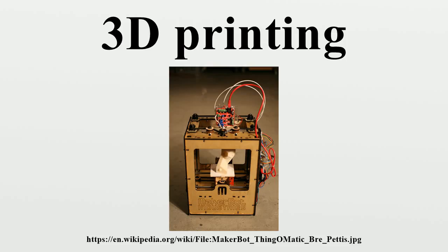Inkjet printer systems like the Objet PolyJet system spray photopolymer materials onto a build tray in ultra-thin layers until the part is completed. Each photopolymer layer is cured with UV light after it is jetted, producing fully cured models that can be handled and used immediately, without post-curing. The gel-like support material, which is designed to support complicated geometries, is removed by hand and water jetting. It is also suitable for elastomers.